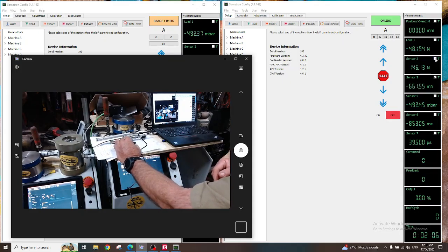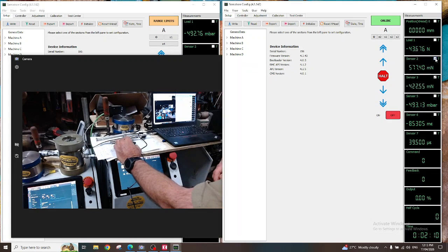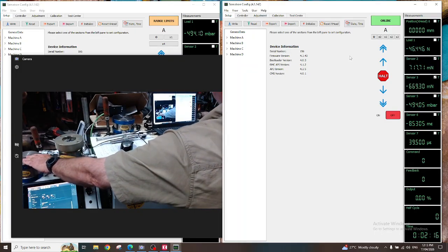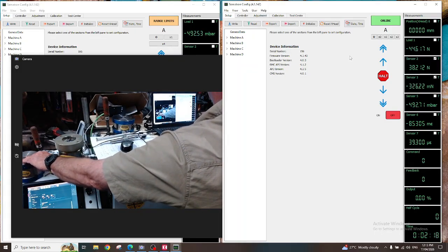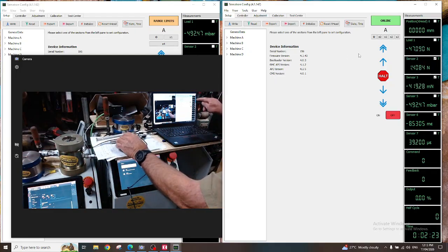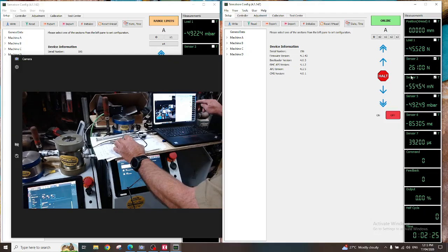I'll just show you that one for the moment. I'm just going to tick the tare button. So it's got 145 newtons on it. I'll tick it. So it's gone down to millinewtons because there's no load on it. It's actually this load cell over here. So if I put any weight on that load cell, you can see up here we're dancing around in the millinewton range.